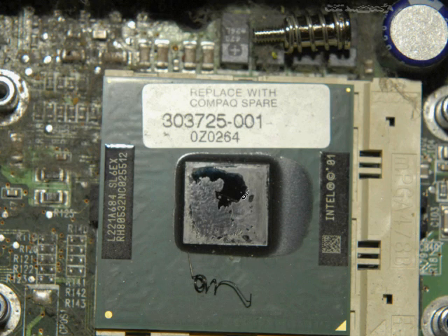If I have to remove the whole heatsink, though, when you go back to the CPU, just remember that you have to use the same standard practice to install the CPU here and to properly cool it that you would with a desktop. In other words, there was thermal paste on top of this. I would want to clean the excess old thermal paste off. You can use isopropyl alcohol to do that. I could clean that off and then put some more thermal paste on, reinstall the heatsink or add a new heatsink, and then hopefully we'd be back in business.